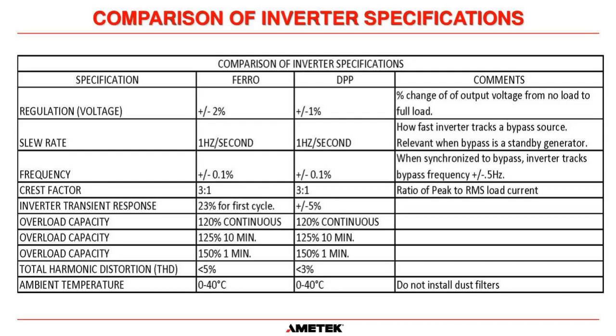Okay. Years and years ago, these detection circuits were just a peak detect based on a true sine wave waveform, when all we had were linear loads and resistive loads, things like that. And in the 80s, when switching power supplies started showing up, it caused problems. So we had to redo the detection circuits. So it's important that the inverter now is able to respond and not detect an overload, even with a high crest factor. Okay, so that's all just in the controls.